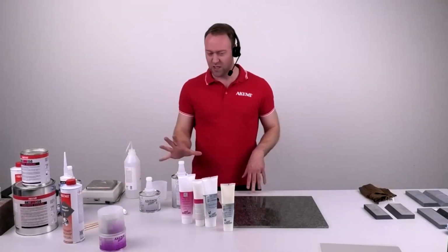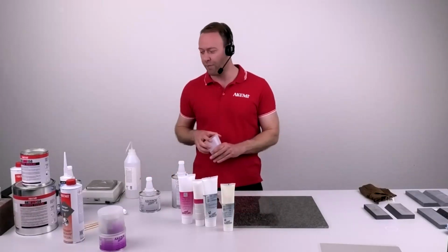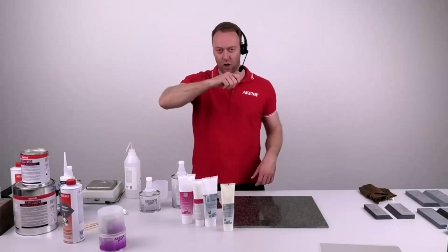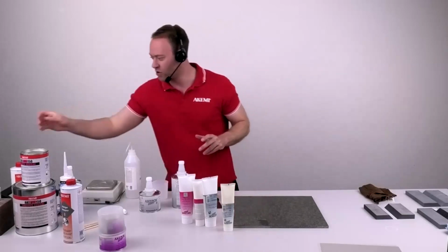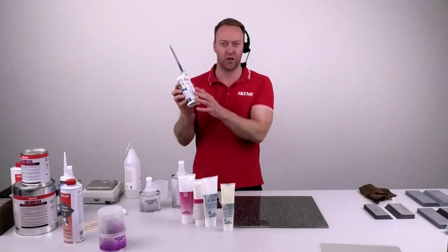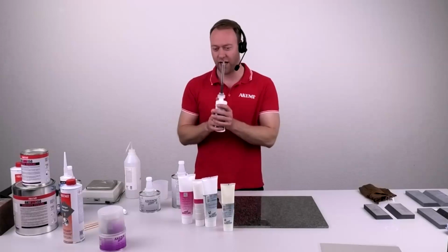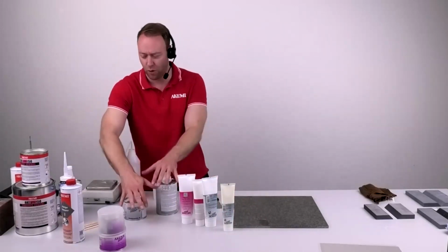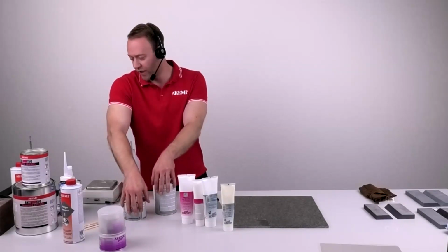But when it's 1:1, you can use something like this, a cup, or you take these scoops, two spoons of A component, 1 spoon of B component, then it works. When it comes to cartridges, no trouble for you because the mixing ratio is already given by the cartridge. You only have to put the mixing nozzle on it. So there's no problem here. But when it comes to cans, especially epoxies, better use a scale to get a proper mixing ratio.